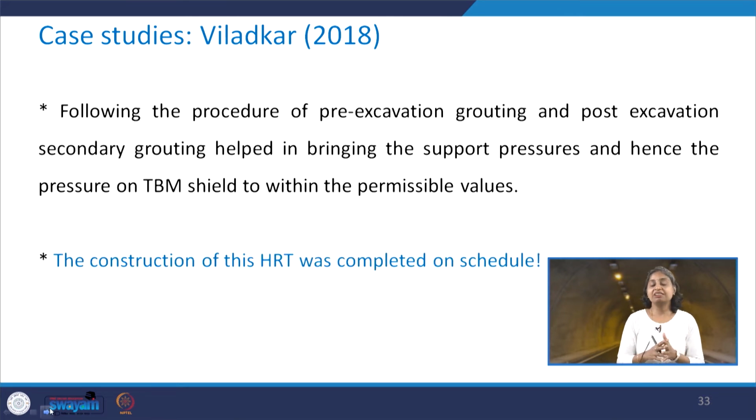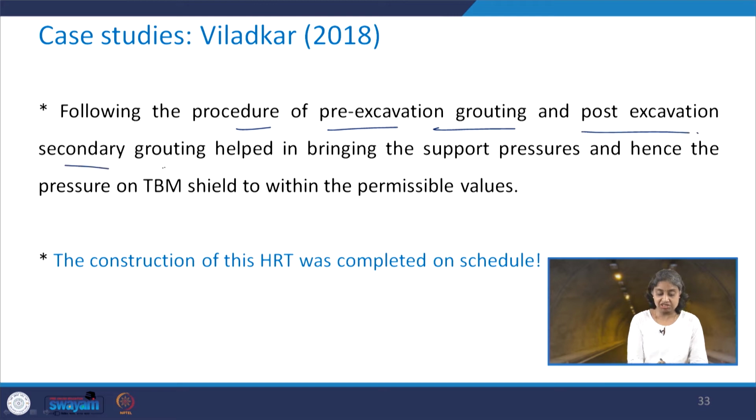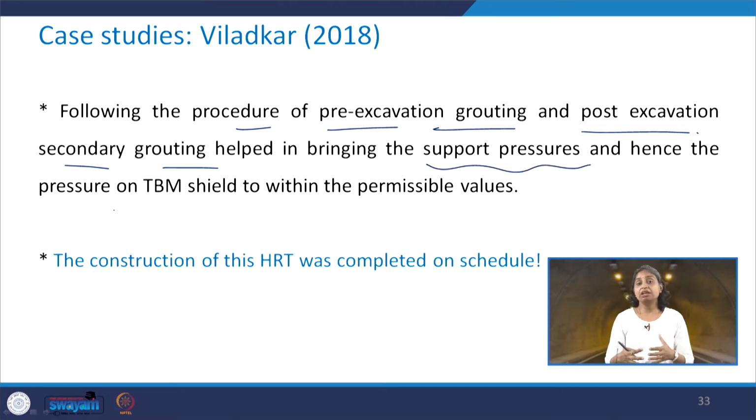So what is done in these cases was that some pre-excavation grouting was done, and that helped in the excavation of the final tunnel. So following the procedure of pre-excavation grouting and post-excavation secondary grouting, it helped in bringing the support pressures and therefore the pressure on the tunnel boring machine shield to be within the permissible value.